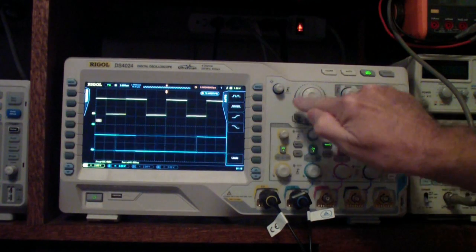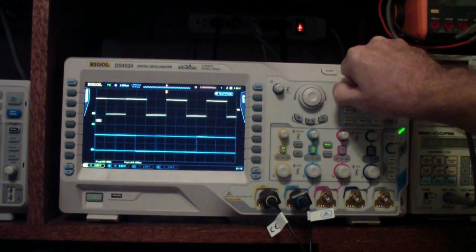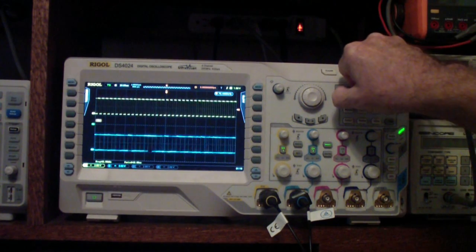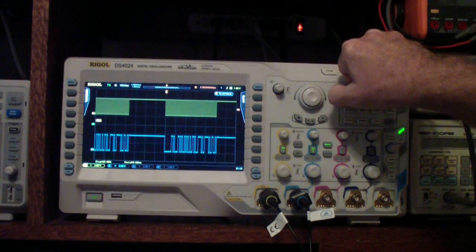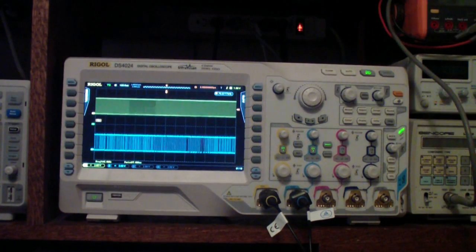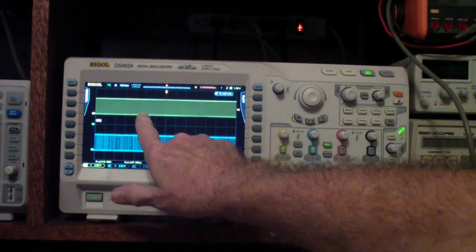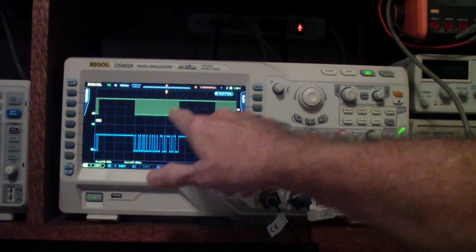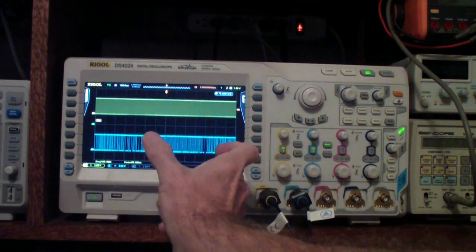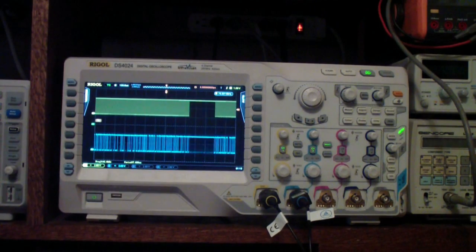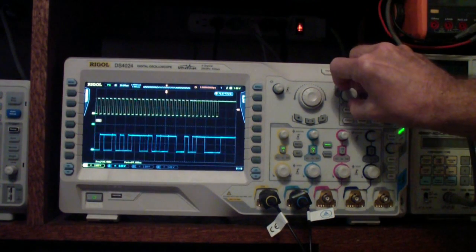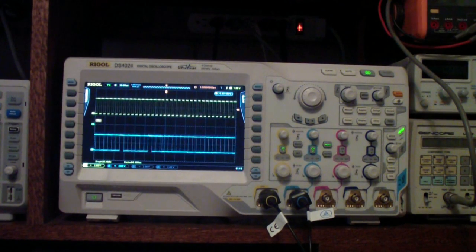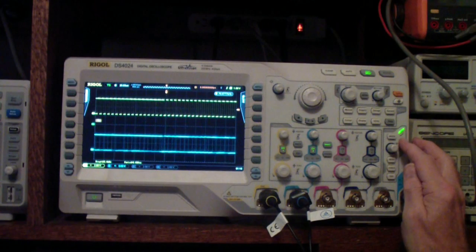And what I'm going to do is lower the time base, that is, longer time per division, until you can see what's going on here, and you'll notice there are some gaps, times when the clock is not sending. That's in between each data group. So you now have the scope triggered. I'm going to run it out a little bit. The second thing you want to do is to set up the actual I2C trigger.